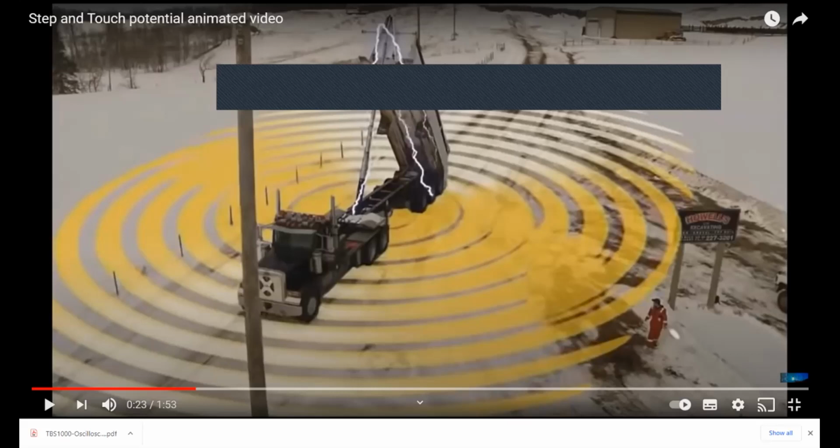Then definitely our object is the ground grid, and because of that current flow through the ground grid, the surrounding area will be under the influence of voltage gradient. But if you move far away, you will find some area surrounding this grounding grid where there is no impact because it is further away. So the resistance between our grounding object within our grounding grid and the remote earth is the ground resistance.